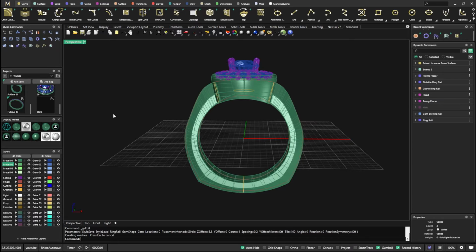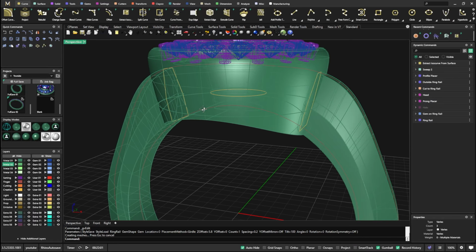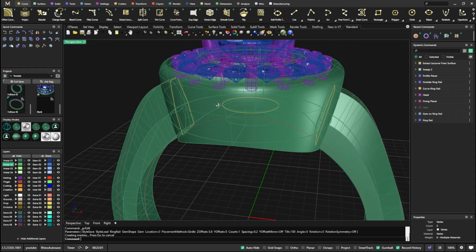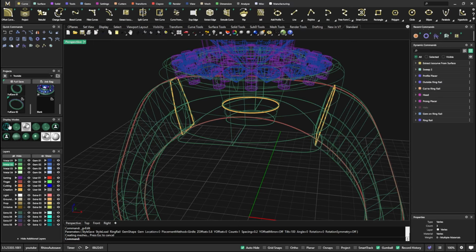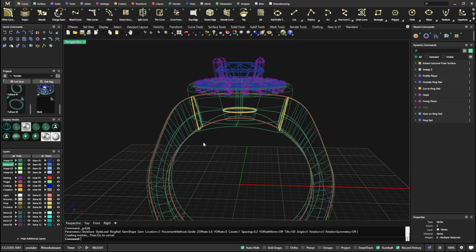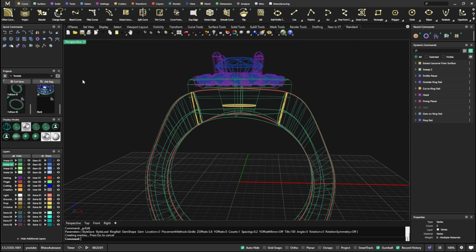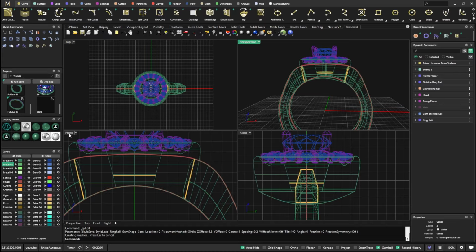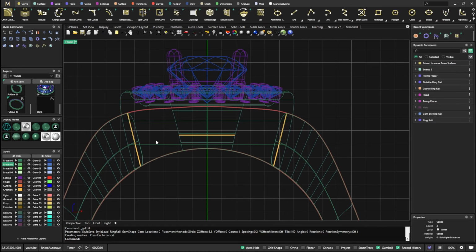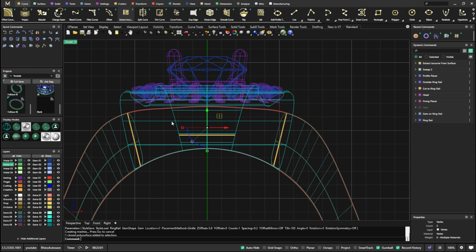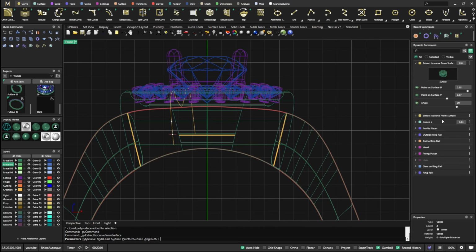Right click, okay, and now that curve, maybe I didn't accept it. I don't know if I did or didn't. Let's click here. Yeah, maybe I clicked it off, but anyway, we can still work with it. So here's our halo. Let's go back to that extract ISO curve, select the surface, and it's putting it in that direction. We'll change it to 180. Now we can drag it up, maybe somewhere around here where it's going to cut.